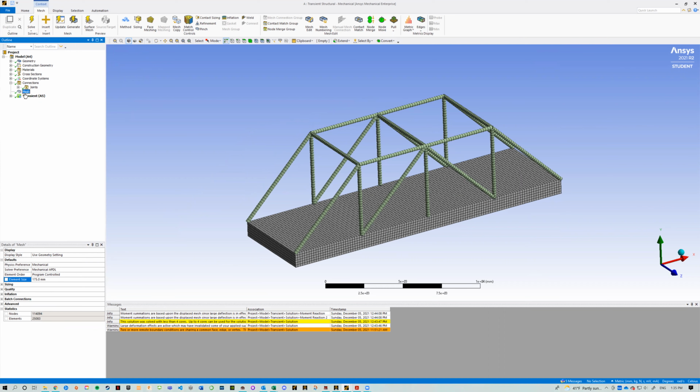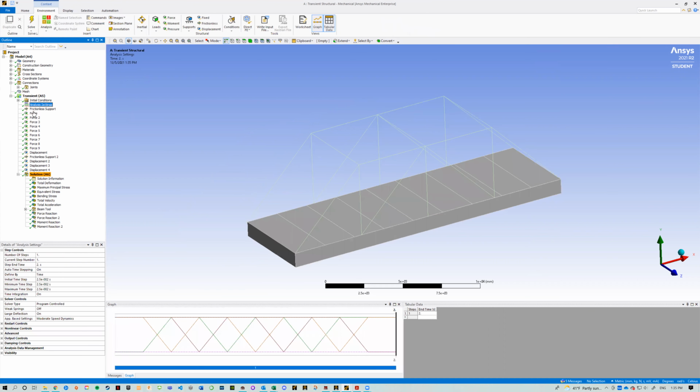Initially you can also set up the analysis settings and change the step size. So this is the biggest I ever made. This step was 0.025 seconds. All of the element sizes above 200 millimeters, including 200 millimeters, were simulated at 0.01 seconds, a smaller step. So you get a more granular output, but I just wanted to test a smaller element and see if it gave me different outputs.